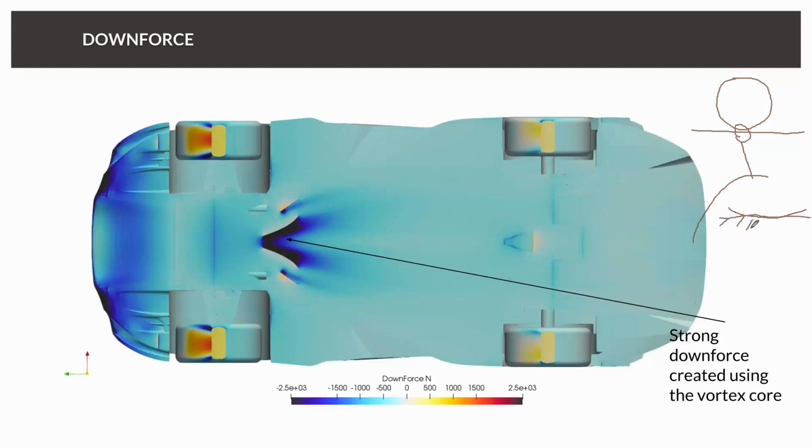We have the tire on the road, and in theory you would think that the tire and the ground are touching only on an infinitely thin line. This means we have two problems. The first problem is that it becomes very difficult to mesh, just from a geometrical point of view, because they are touching on an infinitely thin line, and it becomes very hard to resolve this small angle with a tetrahedron or hexahedron.